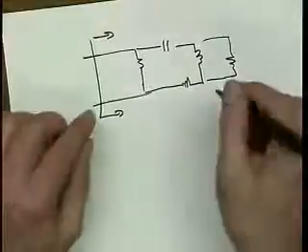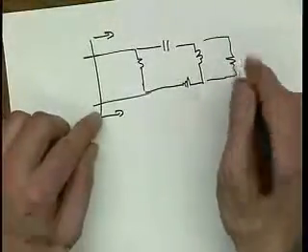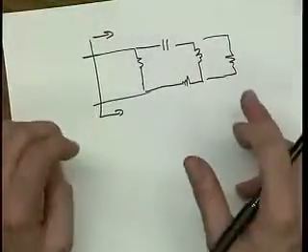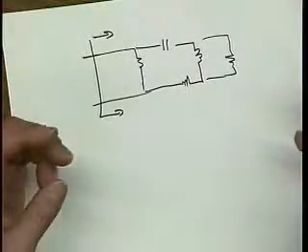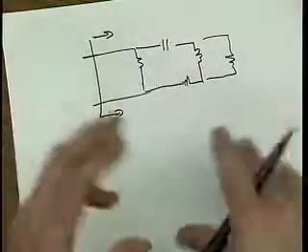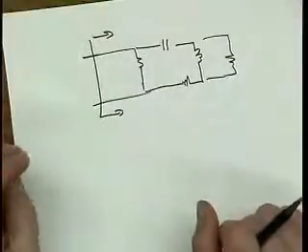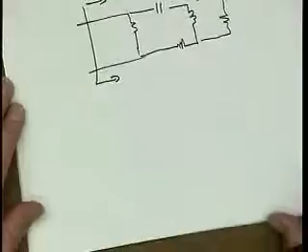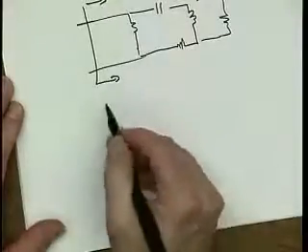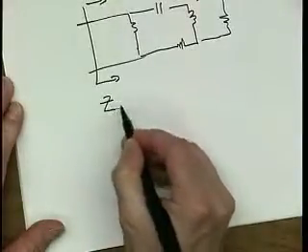Then, of course, we could now replace every resistor with an ideal resistor in series with a voltage noise source and parallel with a current noise source, and then obviously calculate this, analogous to what we did for the resistor. That would work. It would be a lot of work. A simple thing is to figure out what is the impedance of this thing.